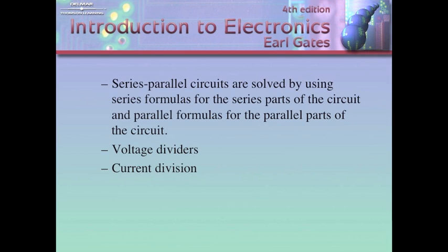I agree with that. Same thing here. We can determine what size resistor this needs to be by R is equal to E over I. If I've got 2.55 amps flowing up through this resistor, and I've got 20 amps flowing up through this load, how much current is going to flow up through this resistor? Very good. 22.55 amps.